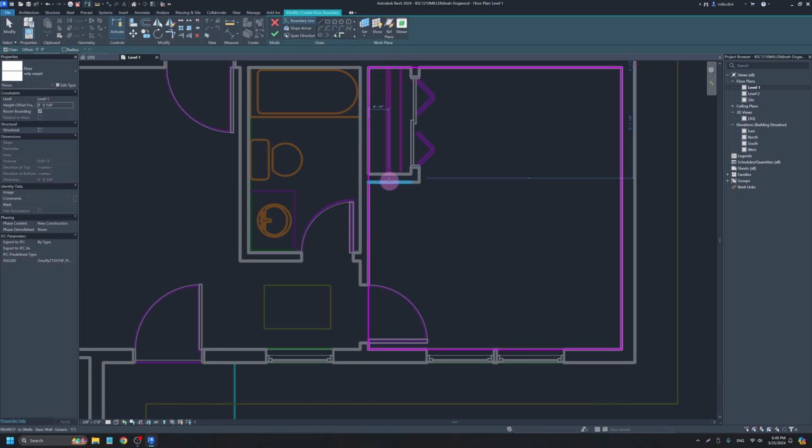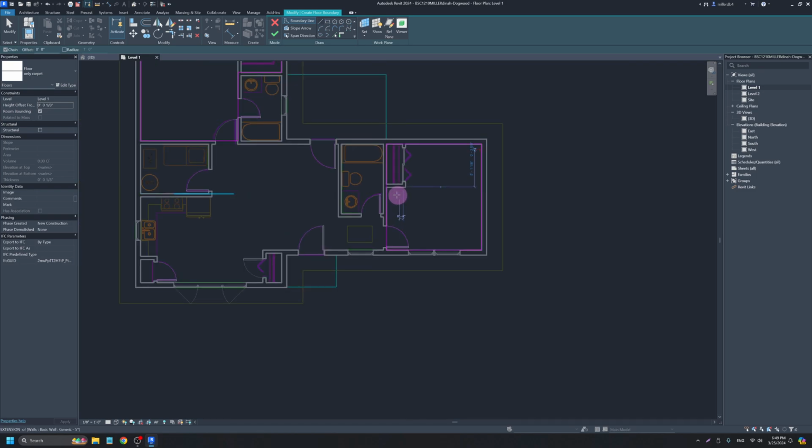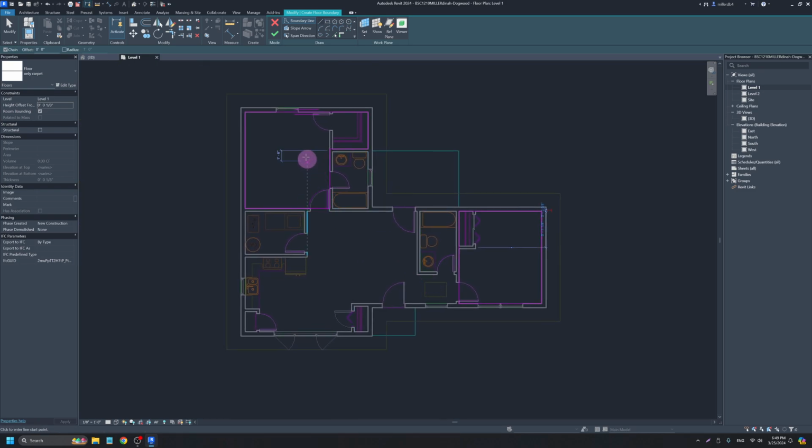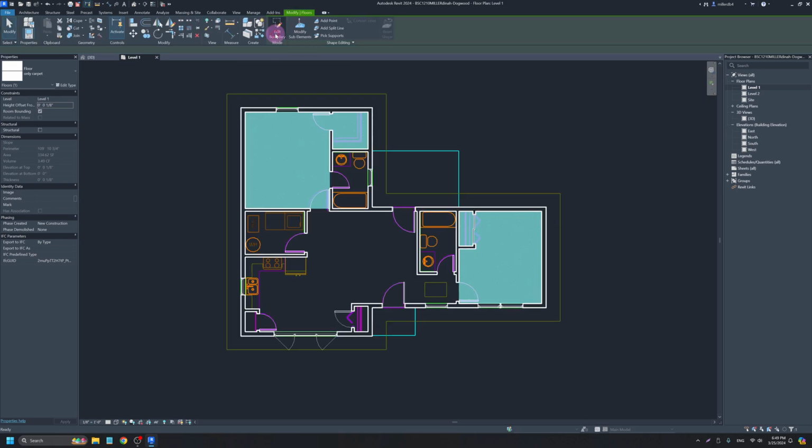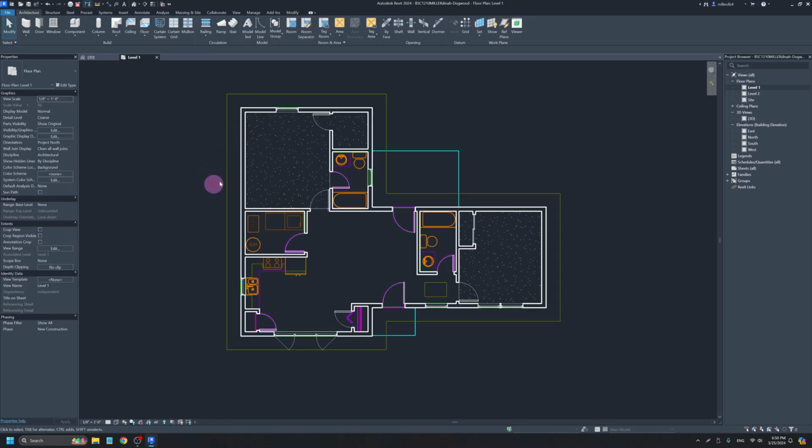I'm aware that like there wouldn't be carpet underneath this stud. So I've got my 2 places. It needs to be one complete closed loop. And then I've got my height offset of 1/8 of an inch. And I'm going to click OK. And you'll notice with carpet, it puts a little hatch there. We'll discuss that in just a bit.